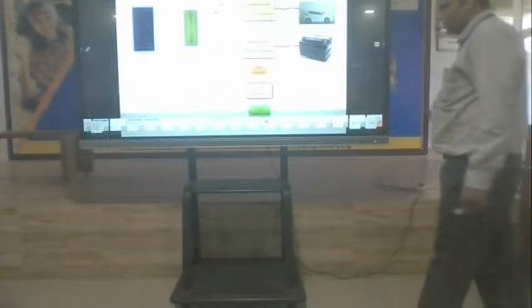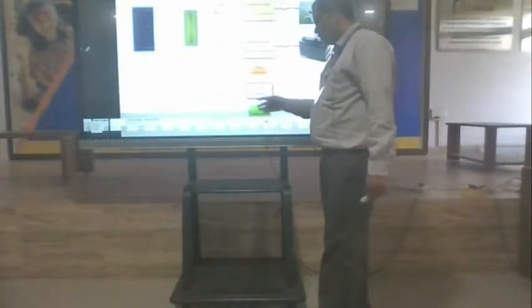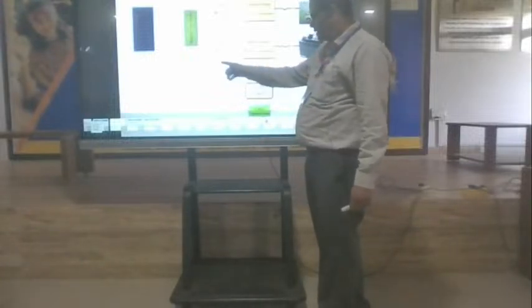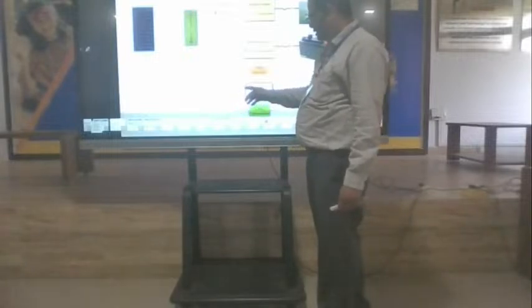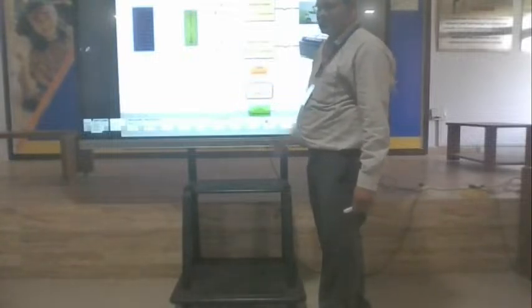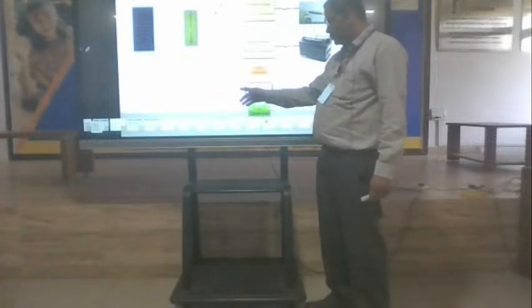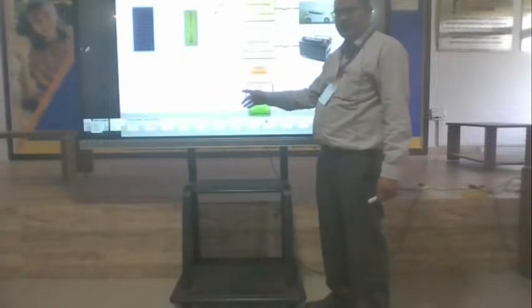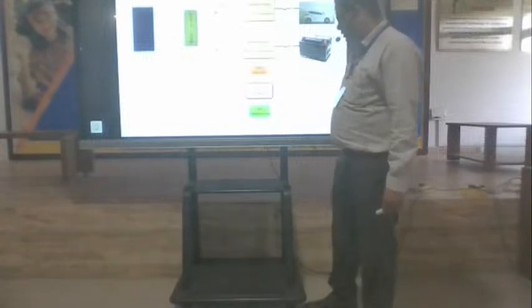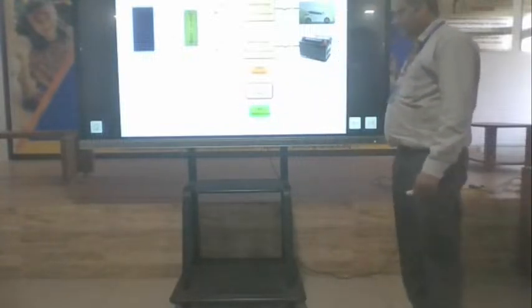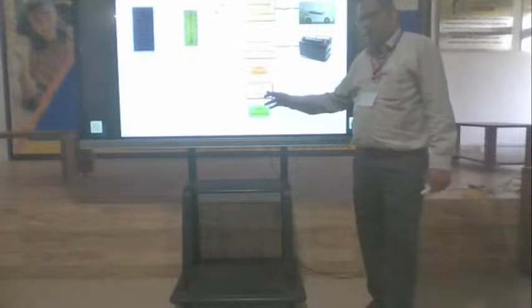Here we have the DC reference voltage, and from the grid, based upon the voltage available, the grid voltage is always maintained constant. So if any difference is there, an error signal is generated, right? That error signal is given to the fractional order PI controller.